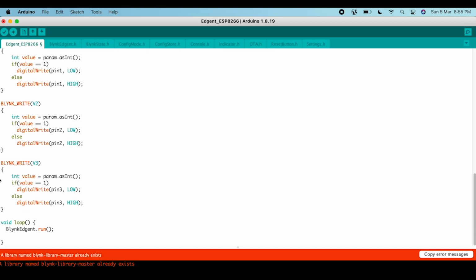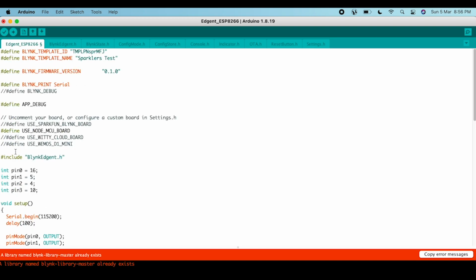In that case, you don't need to define any of the functions, because if you define a digital pin, Blynk will do everything for you. It will make the pin high and low automatically. You don't need to even define the pins.